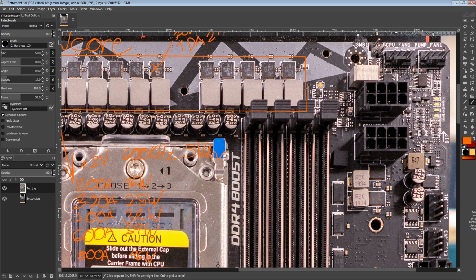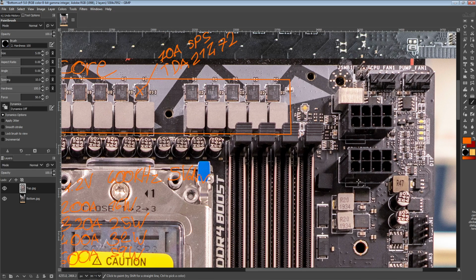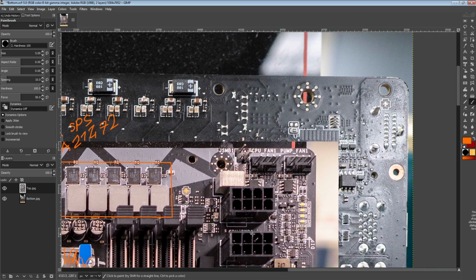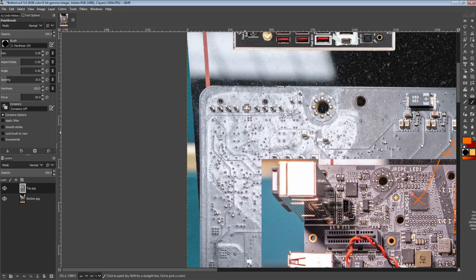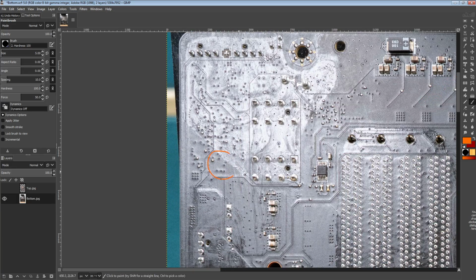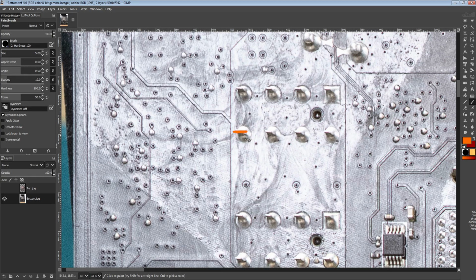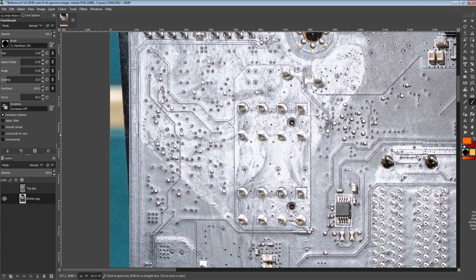Which does mean I'm not really a fan of this dual 8-pin power configuration on this motherboard specifically, because MSI uses, if we hide this, you can see that these are flat tabs coming out of the holes for the power connectors. MSI uses the folded metal power connectors, and the folded metal pins are the lower current variant of the 8-pin power connector.